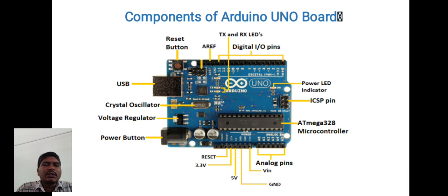the microcontroller. Here the ATmega328 microcontroller is normally used because it is a single chip microcontroller from the Atmel family and it is an 8-bit controller. It combines memory, that is SRAM, EEPROM and flash, and also inbuilt ADC, SPI serial ports and input output lines, registers, timers, external and internal interrupts and oscillators. That is why the ATmega328 microcontroller is most preferably used.